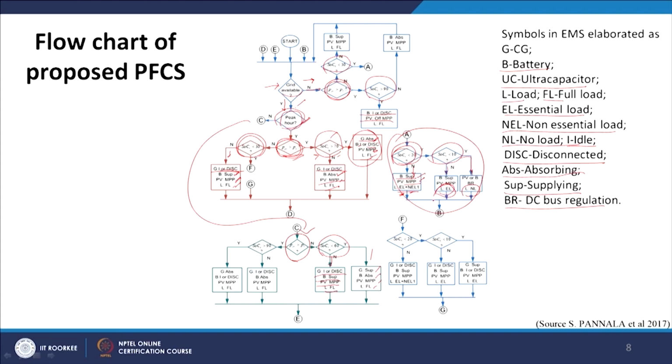Okay. And if it is less than 10, then there is no load that I can cater, meaning I do not have grid, my PV is also not greater than P load, and my batteries also do not have energy. So finally I have to keep on curtailing the non-essential loads, and finally I will come to a condition where the grid is not there, and my microgrid is also not able to meet the basic loads. So, this is the whole scenario of the control strategy which has been incorporated.